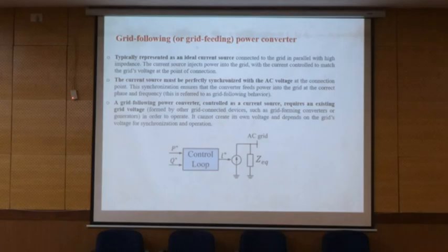Yeah. The idea is that, for example, if you have a 1 ohm impedance and you parallel it with another 1 ohm, the equivalent will be equal to 1 over 2. Okay? But when you have 1 ohm and another is 100 ohm, it is 1 times 100 over 1 plus 100, which is near to 1.